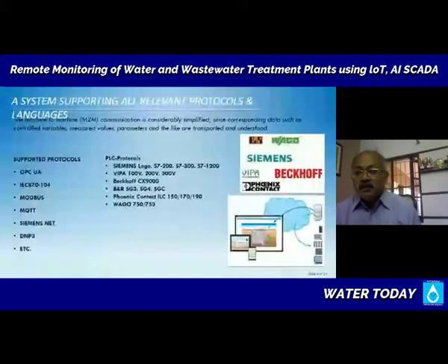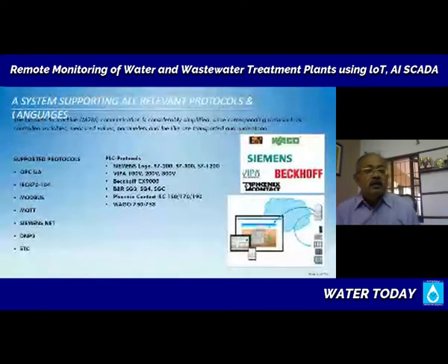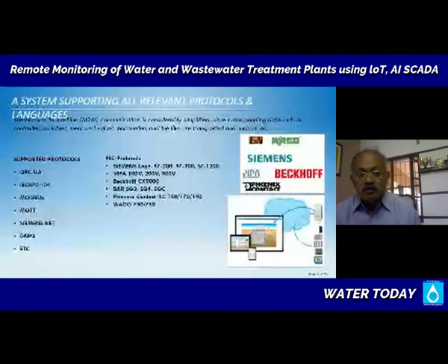Now, one thing that I would like to point out to everyone attending here is please make sure that if you are using any system, you select one which follows some internationally established standards. Because if you get lost in a vendor specific communication system, then you're always locked in with that one vendor. Whereas if you are using a Modbus protocol or a DNP3 protocol, DNP is widely used in power systems.